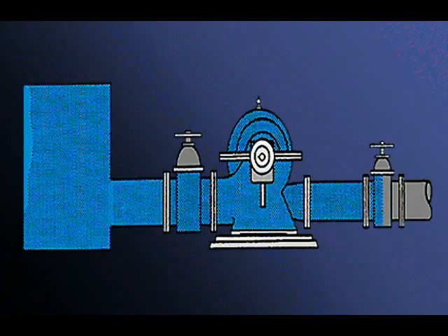Starting with a flooded suction pump. This pump is under pressure. It has a positive suction head. A pump in this arrangement will seldom lose its prime, and will likely only need to be primed after it has been opened or replaced.